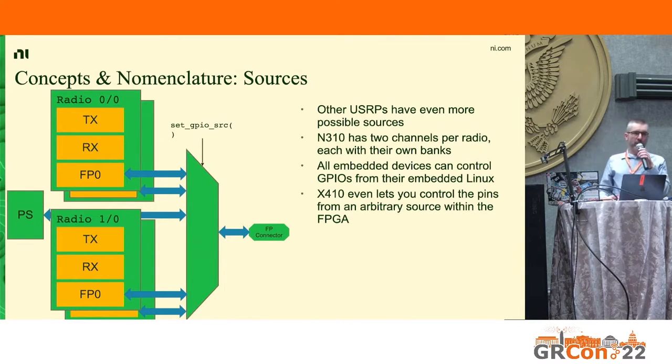That's a mode where we yield control of those GPIOs to software that is not controlled by us. And that's when you go back to the Raspberry Pi programming mode. So you can say, okay, front panel connector, top 6 pins, I'm just not going to care about those. I'm just going to hand them back to the user, to some random software running on the device, to control those. But otherwise, it's the same principle.